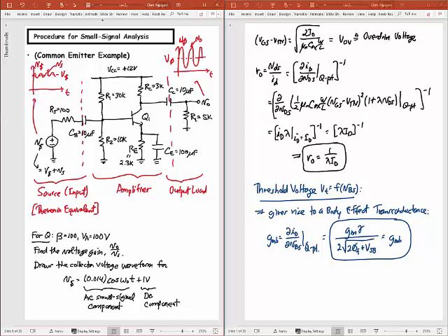And in this case, I'm assuming that's resistive. You'll notice that I'm connecting my input source to the amplifier with a capacitor. The capacitor is 10 microfarads, and the capacitor at the output is also 10 microfarads. What's happening here is that if the frequency of the input signal is large enough, this capacitance becomes a short. And this capacitance becomes a short.